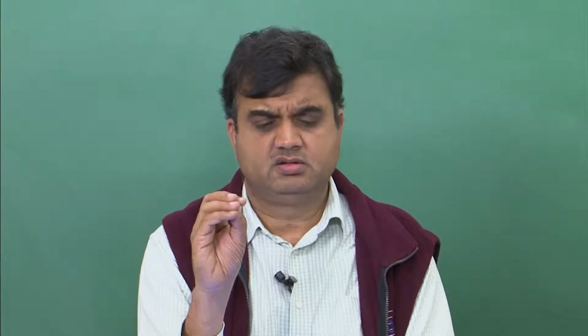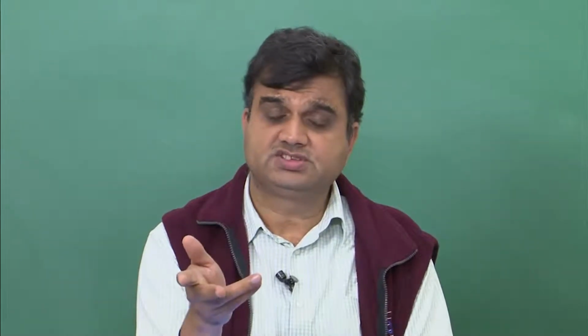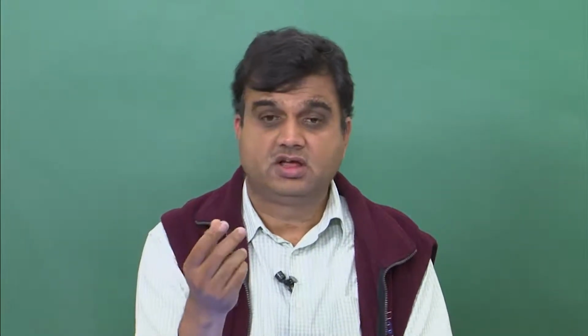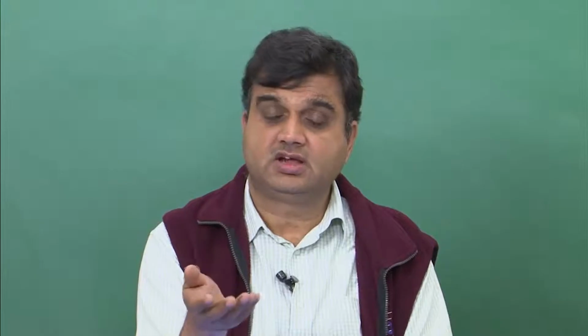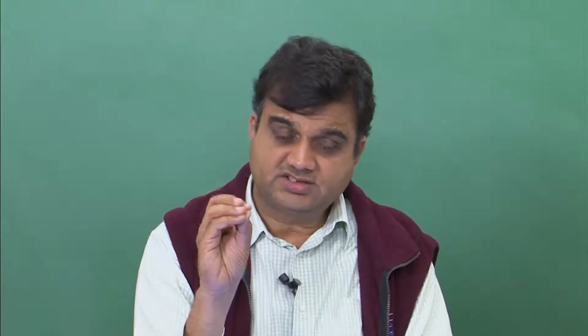In a speaker you have current which goes into a coil, and this current cuts the magnetic field lines, and because of this we generate this force known as Lorentz force, and because of the force the diaphragm of the speaker moves up and down. You can use an existing speaker, and if it's fairly sensitive you can use the same speaker to behave as a microphone also, but the mechanics is just inverted.